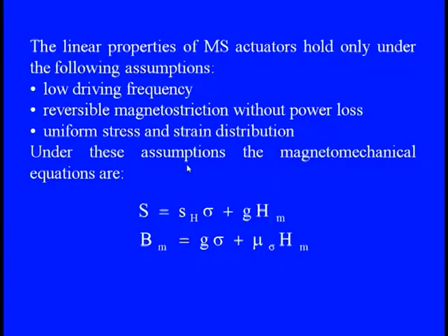But when we set up the relation, we can simply assume a linear property of the MS actuator, and it only holds when we assume a low driving frequency of the entire system, whatever the exciting frequencies are. Then we need to assume a clear reversible magnetostriction without any power loss.